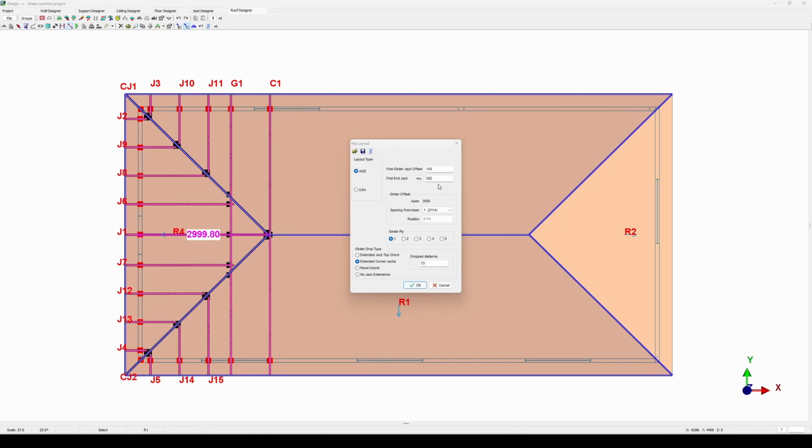And with this setting, you have the ability to control the spacing and the set position of your girder placement right there. Now, in this case, we are placing the girder on the first position away from the apex. You can see with that dimension right next to it, that dimension is indicative from the outside of your wall to the position of your girder right there.